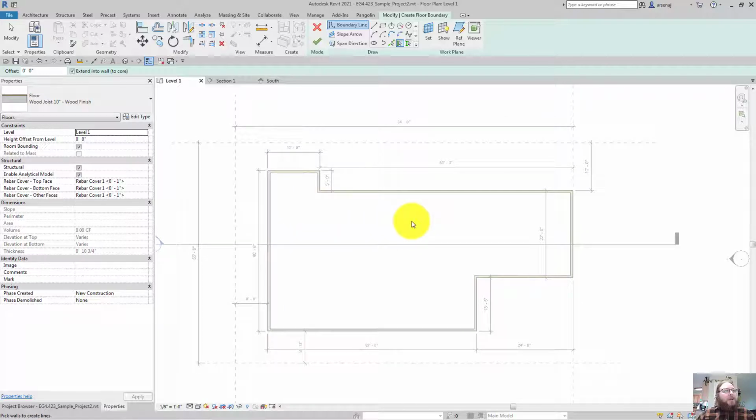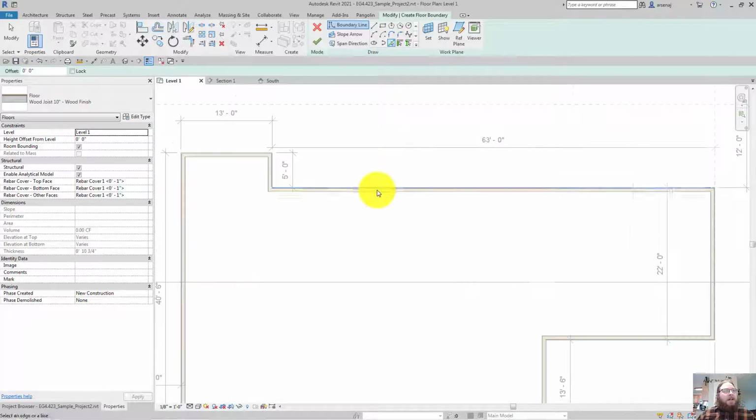So when you're in here laying out the walls, it's going to want you to draw boundary lines. There's several ways to do that. If it's a rectangular building, you can have this rectangle, you can have circular, all these different options. You can just draw lines if you wanted, but the quickest way is either to pick line, which allows you to create the lines by picking, just by tabbing or picking, and it'll create your line wherever you want it.